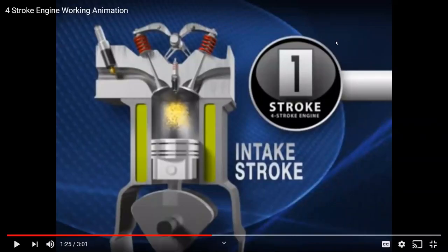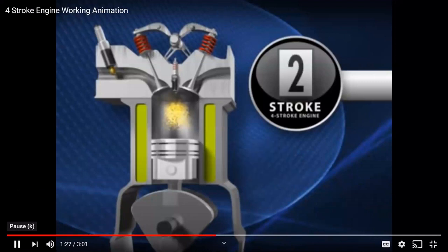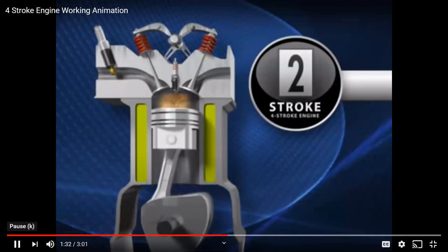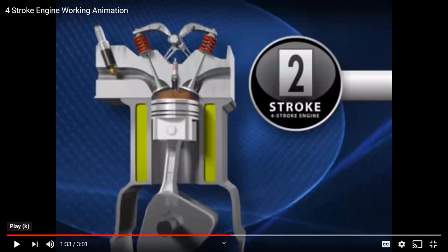Actually, what I'll do instead, at the risk of being tedious, I'm going to go through this very briefly just one more time, and I will pause and skip past the exhaust and intake so you can more clearly visualize how this four-stroke cycle matches the four-process PV cycle. Okay, so right now you're about to watch the adiabatic compression from the bottom right to the bottom left on the cycle. On the second stroke, the piston travels upward, compressing the air and fuel to make a highly combustible mixture. Okay, that was the adiabatic compression.